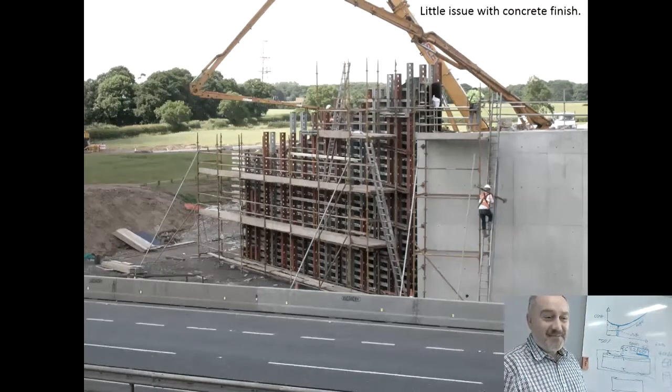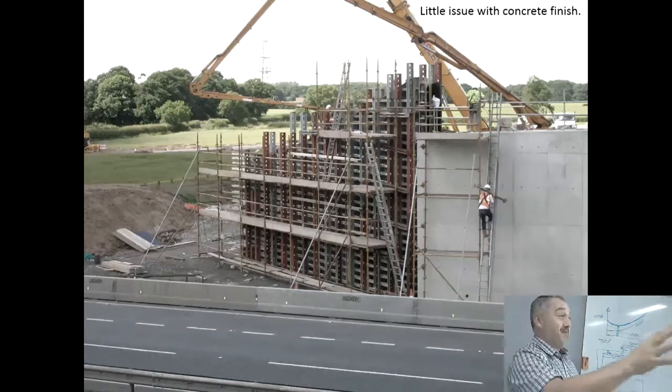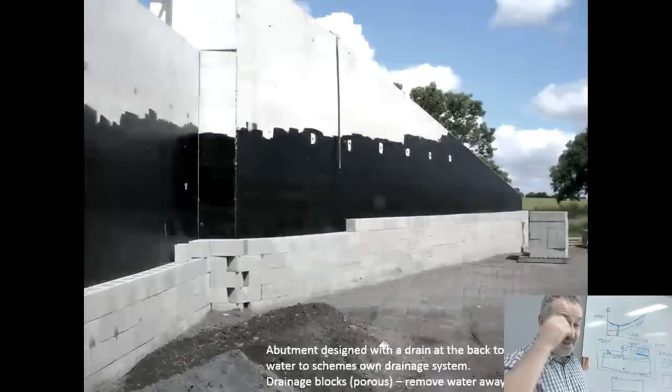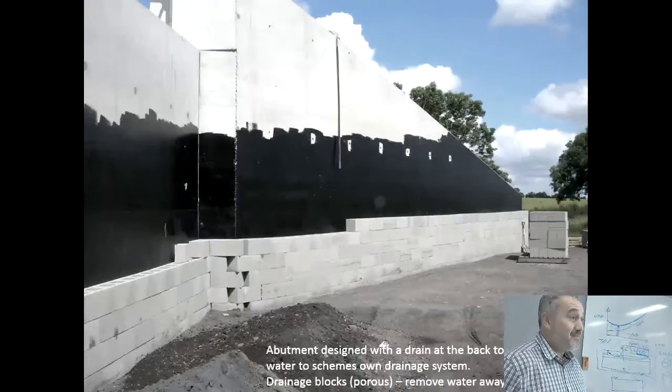Okay. Yeah, it'd be worth having a look at the specification to see whether you're allowed to do that. But yeah, I'm sure everybody has their different ways of approaching that. So it may be that for embankments it's perfectly fine to do that technique, because you've got air holes and all this type of thing, or there might be some honeycombing where you can see the aggregate. What would you do then in that situation?